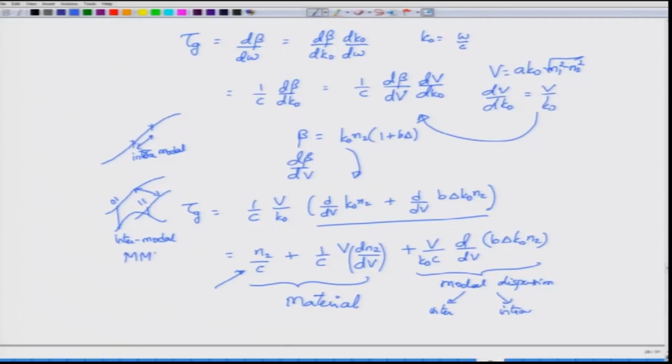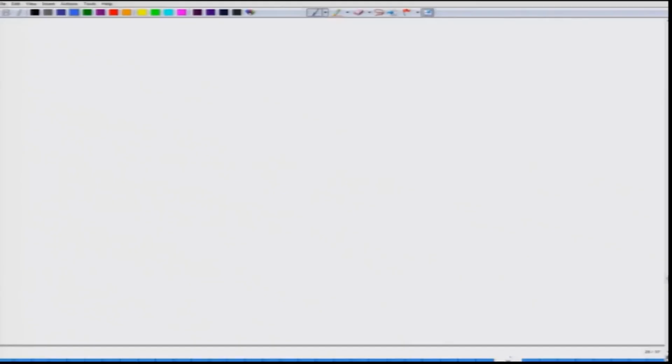Intermodal dispersion is quite common, and in fact is one of the major problems in multimode fibers, whereas intramodal dispersion, sometimes called simply chromatic dispersion, is an important parameter in single-mode fibers. But our formalism would simply want you to know what beta 2 is, and therefore does not really depend on whether you have applied it to a single-mode fiber or a multimode fiber. But it is interesting to see that this modal dispersion comes from two effects, as I have told you.